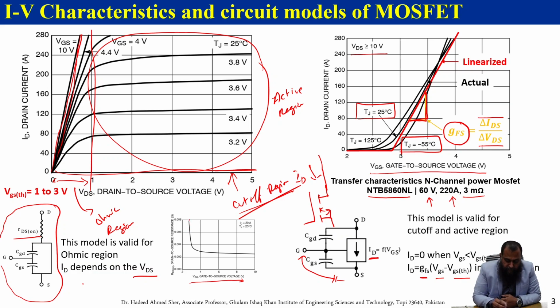As you can see here, it has a high value below the threshold voltage. After it crosses the threshold voltage at this junction temperature of 25 degrees centigrade and at 20 ampere, you can see here that this slope is almost constant. That is, there will be a very small change in the value of the RDS on.